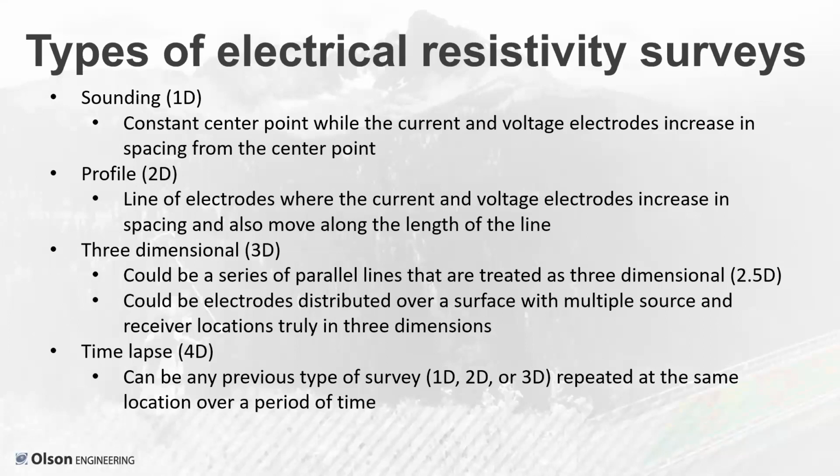These were mainly focused on levees, and when the water level in the river is low, there's going to be a small amount of seepage. And when the water rises up and gets towards flood stage, there's a much higher head difference between the wet side and the dry side. So the seepage increases.